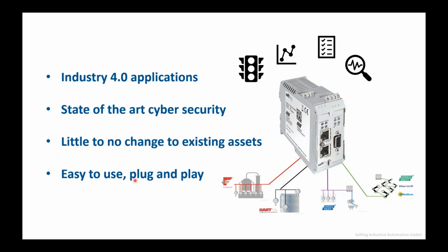I see, thank you. Another question that came in separately is, does your gateway need a separate power supply, or is it a power supply? Yeah, our gateway has to be powered by what's in the field, 24 volts or something like that. It is not a power supply, so it does not act as a power supply to the fieldbus it is connected to. In terms of industrial Ethernet or Profibus DP, every device has to be powered itself.